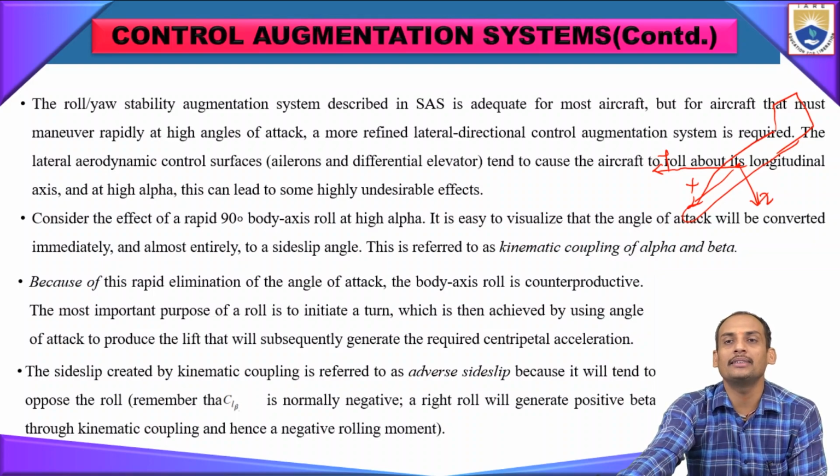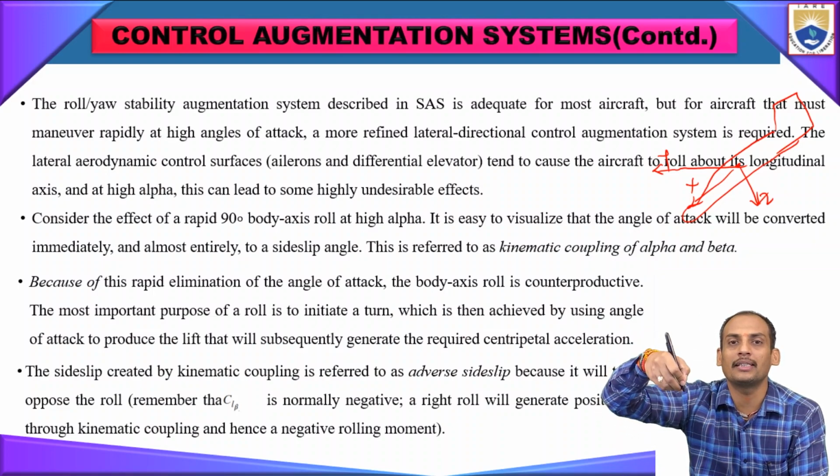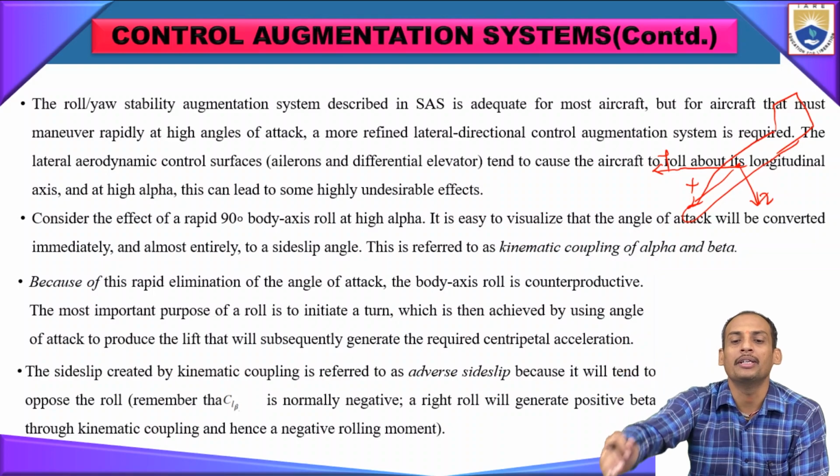It is easy to visualize that the angle of attack is converted almost entirely into a sideslip angle, when we introduce the sideslip angle for making the rolling movement.